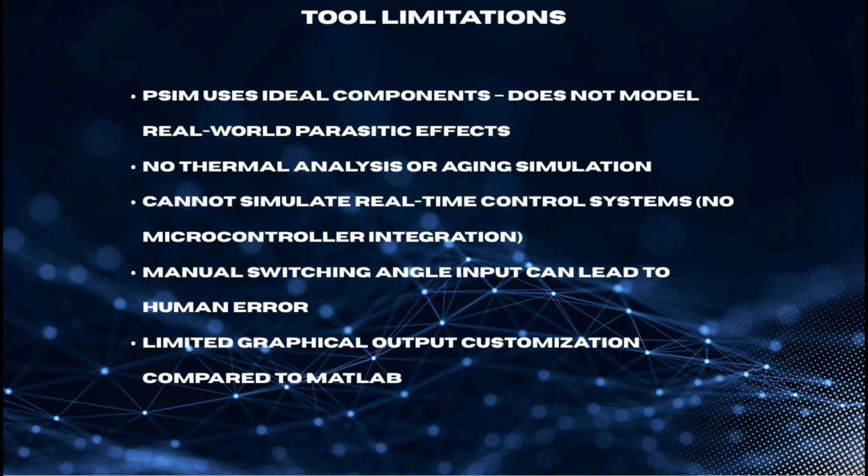Tool limitation became a concern in this project. PSIM uses ideal components, so it cannot simulate thermal effect or parasitic losses. It also lacks real-time control features, requires manual switching input, and offers limited graph customization compared to MATLAB.